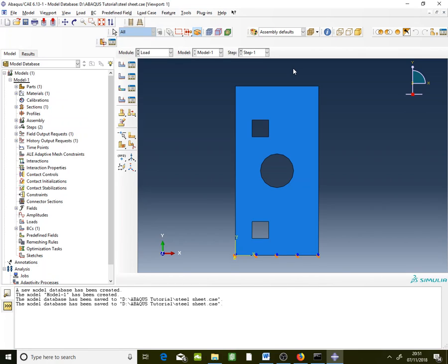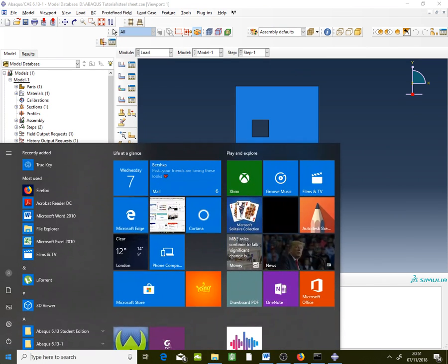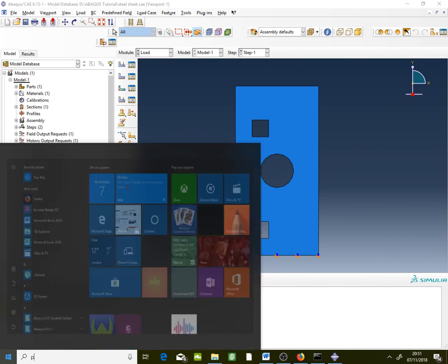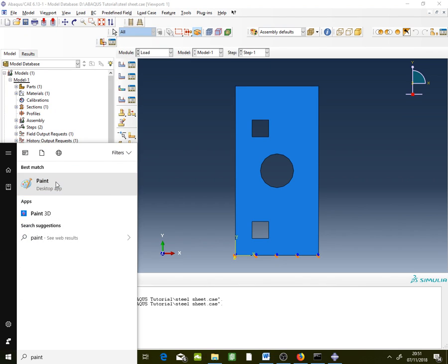Here the load is applied as a displacement, not applied as a load or pressure. The load applied as displacement is very good when you do a nonlinear analysis, because as the displacement increases, the load may increase or decrease. So in displacement control, it can capture the ultimate load. Let's get a better understanding. I'm going to draw something about it.